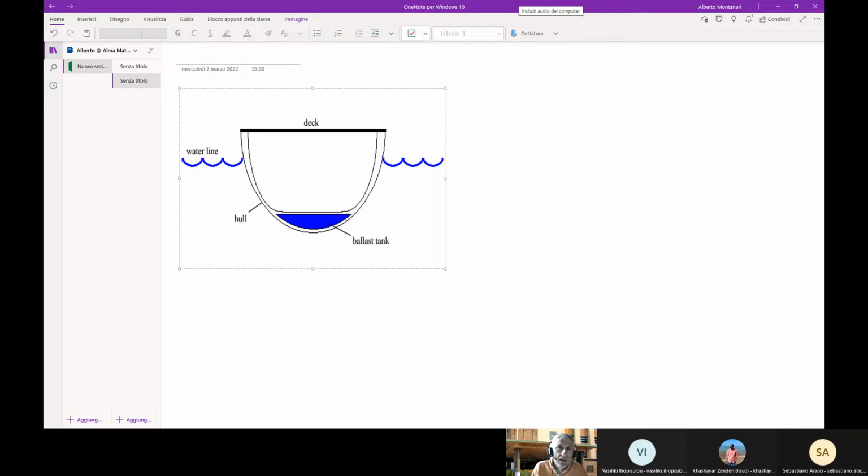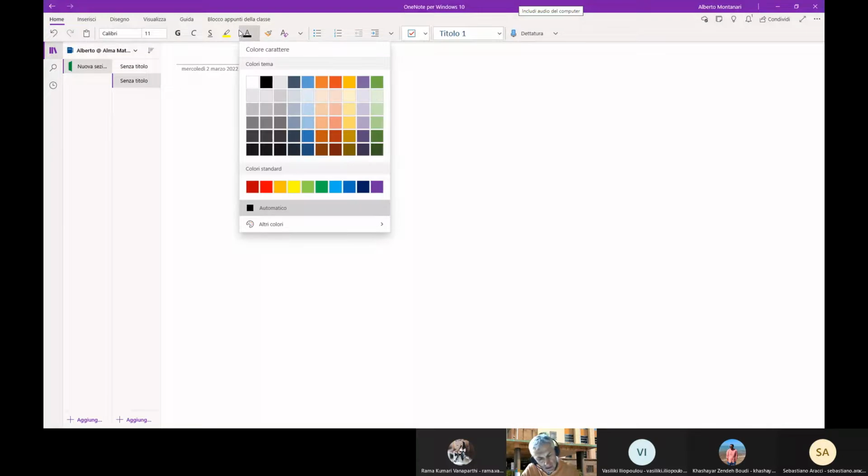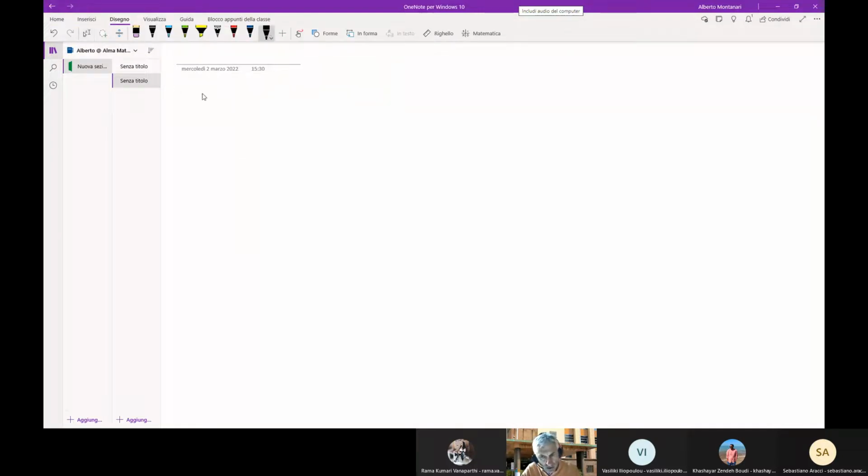Wind is a random process. When we talk about waves, it's a significant random process. Randomness implies uncertainty, of course. Keep it in mind, we have a lot of uncertainty in our design. The presence of uncertainty, in a way, makes empirical relationships necessary, because you have to find an approximate model to manage uncertainty. This is why we introduce these empirical relationships. What I'm writing now in order to estimate the wind forcing is physically based, but at the same time, you recognize that there is a lot of empirism in it. Now, let me write it. I take a black color, just one second. So let's call the wind force, in kilonewton, PW.